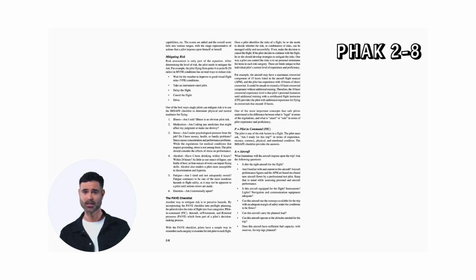A, the aircraft. What limitations will the aircraft impose upon the trip? Ask the following questions. Is this the right aircraft for the flight? Am I familiar with and current in this aircraft? Aircraft performance figures and the AFM are based on a brand new aircraft flown by a professional test pilot. Keep that in mind while assessing personal and aircraft performance. Is this aircraft equipped for the flight? Instruments, lights, navigation and communication equipment adequate?